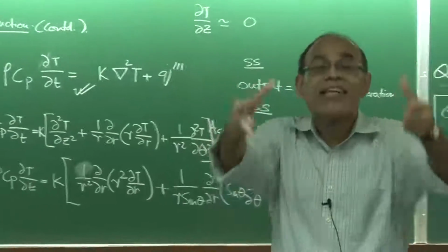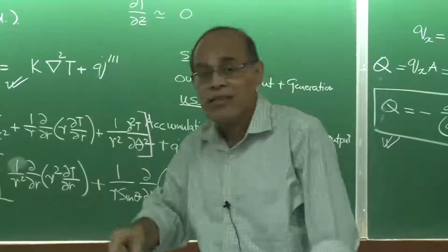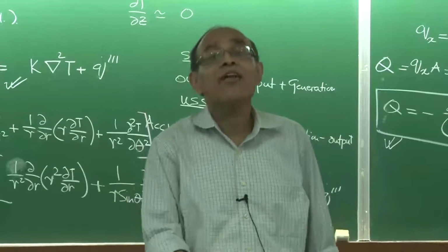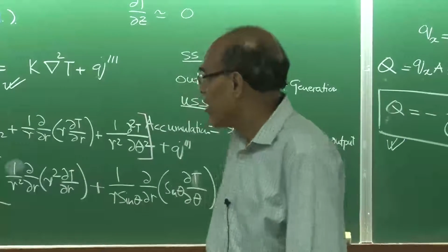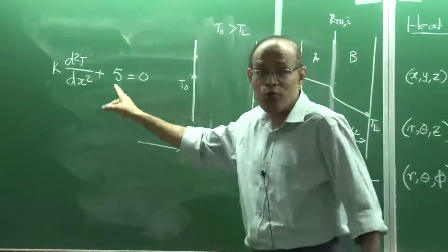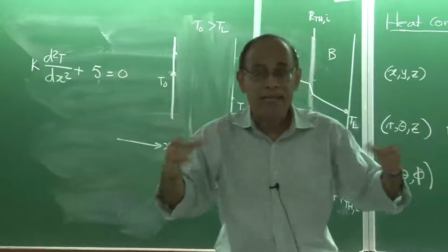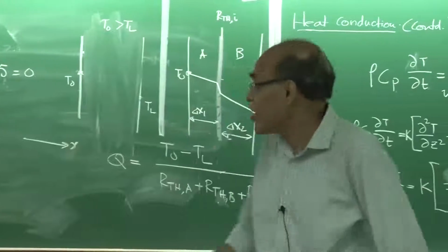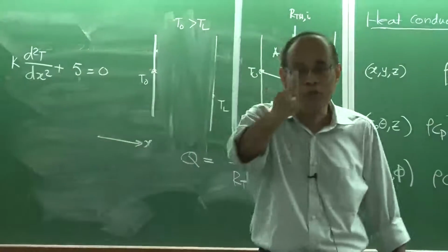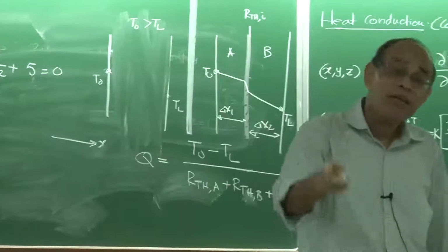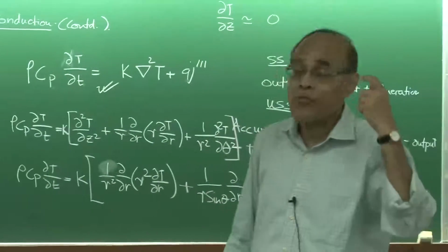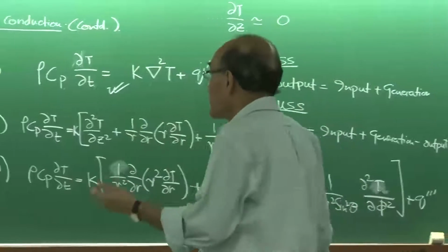Flow through a cylindrical pipe, and imagine that you had only one second order term, that is along the radial coordinate, and we have the pressure gradient term which is constant, because fully developed flow, if you remember, is characterized by a constant pressure gradient. So, this equation is analogous to the fully developed flow equation that we derived for flow through a pipe, where the flow is taking place because of an imposed constant pressure gradient.